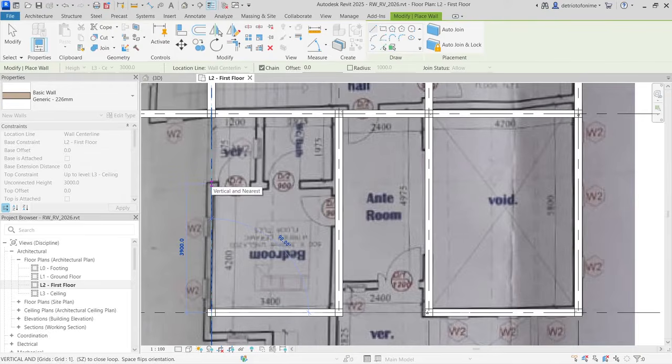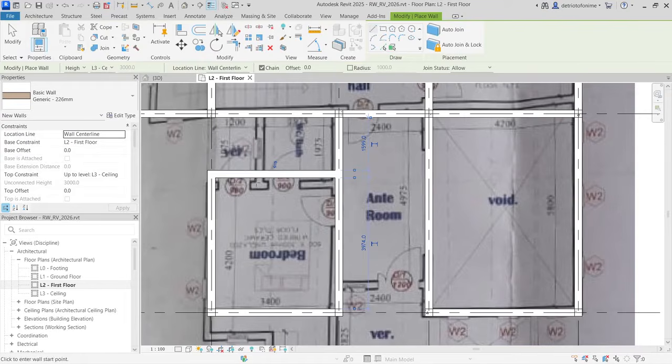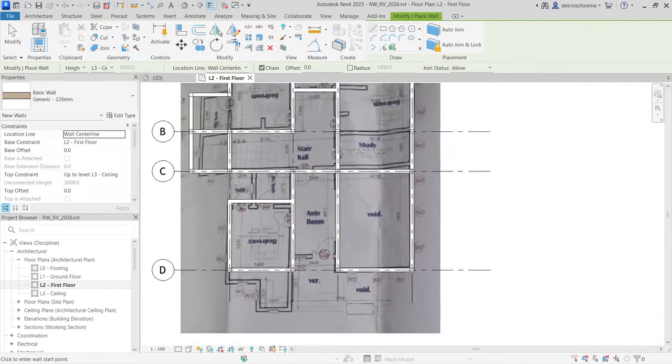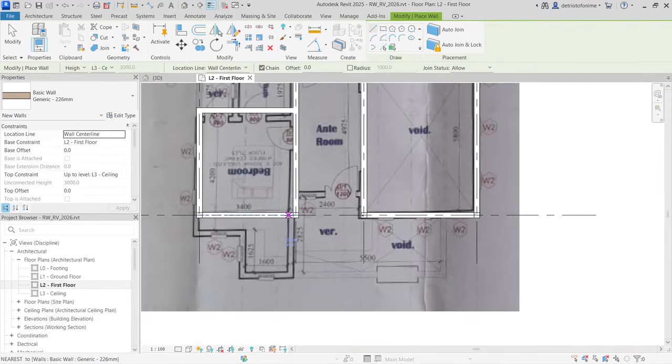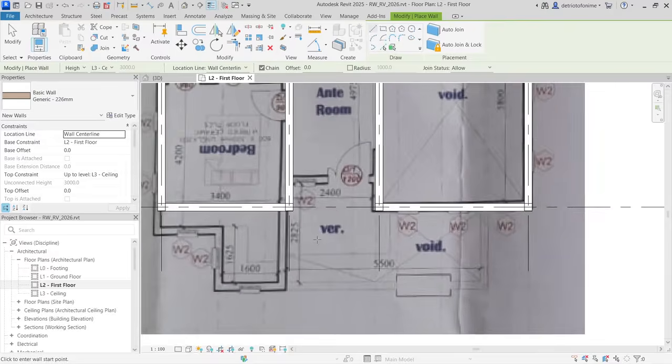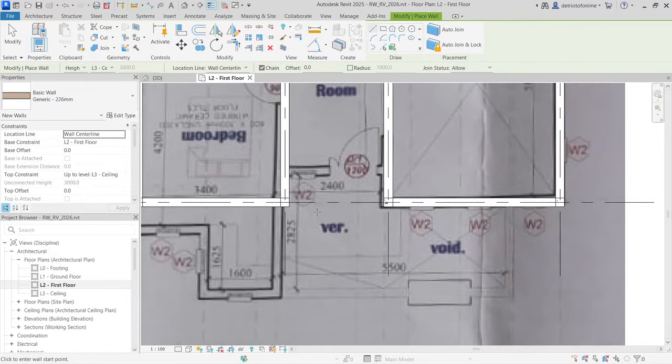meters. So in case you want to factor in the wall, but since we're already starting from the center of the wall, there might not be any need to do that. So we can just select 4.2 and drag it this way. There we go. So this is going to be our veranda. The beam runs all the way down to the other side. So what is left for us to do now is to extend this wall by 2.8.